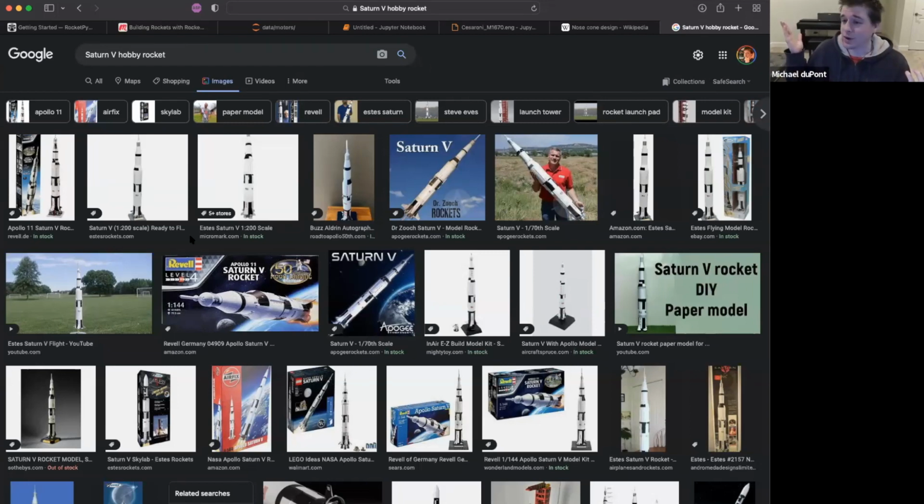But if I launch right here, technically, I can't even fly. I can't fly a drone above 400 feet here, because that's where Class G airspace ends, and anything above 400 feet over most of the United States is controlled airspace in one way or another. But especially in Orlando. Orlando has something called a Class Bravo airspace for Orlando International. It's custom tailored. It looks like a reverse cake. It's a big deal if you mess with their airspace. It's a really big deal.